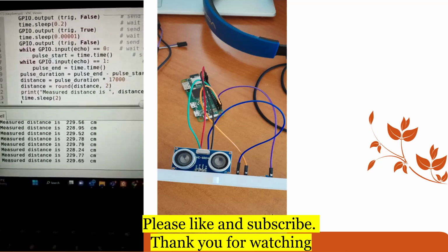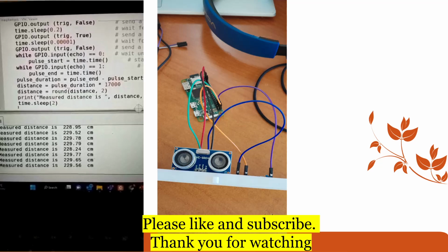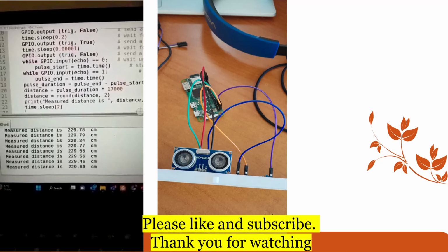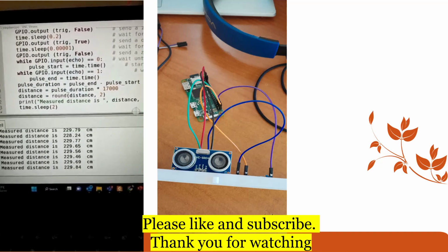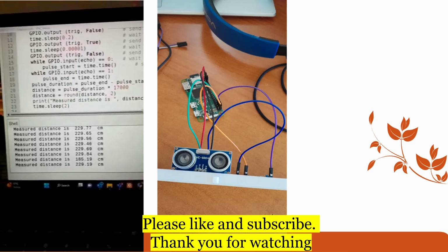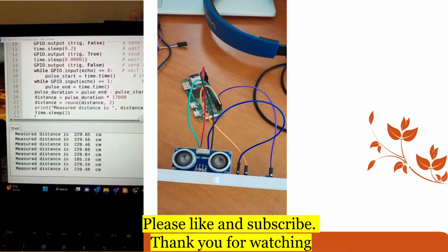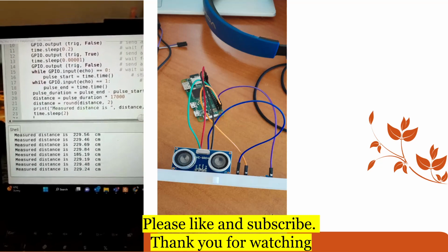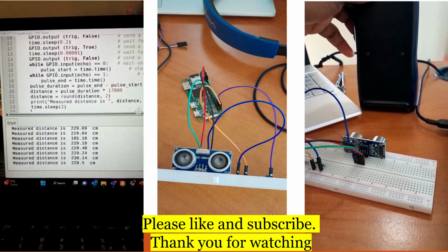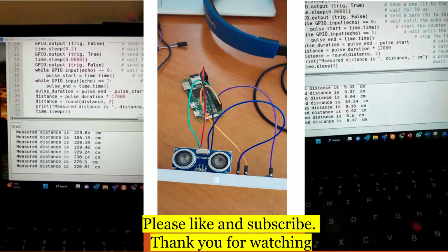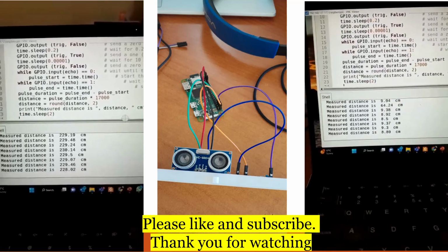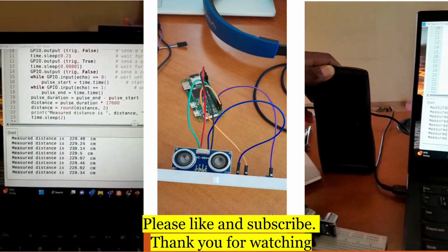You notice some kind of little fluctuation between the previous value and the new value. Like I mentioned, it is as a result of the temperature of the sound wave. The temperature is not constant, the temperature varies. And as you have been taught in physics, temperature affects the speed of sound in air. So you should expect this to happen. So when I bring this on, we add a kind of temperature compensation so that the distance can be more accurate. And so the distance is now 9.3 centimeters. Between the previous value and the new value is not that different.